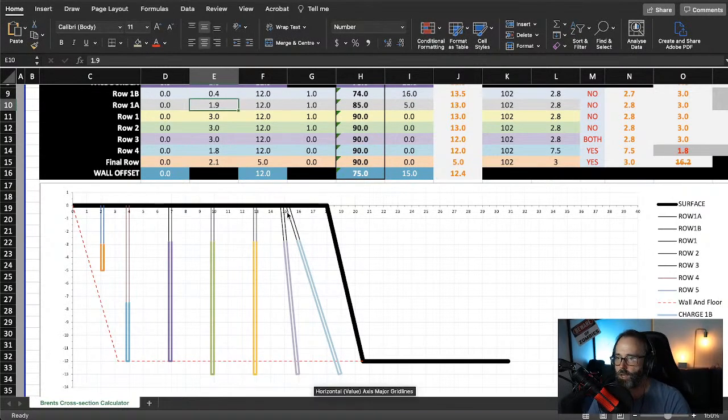The hole, I mean, do you know how big a drill hole collar is? That's a good point to think about. I mean, your drill hole collar is, your cuttings and that. So as you're drilling one hole, the cuttings from that one hole lay out there, and let's say in this case it's 102, so we've got probably a cone of about 300 or 400 mil maybe of cuttings over a 12-meter bench. On a 20-meter bench, maybe it's bigger.